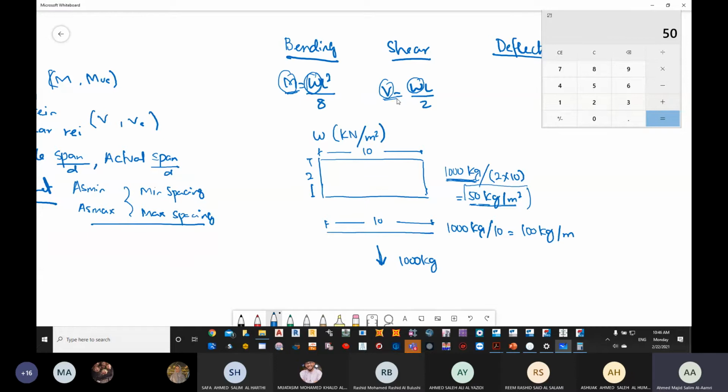And the shear check is without links or reinforcement in case of a slab because of the less loading in the element. So bending and shear, when it comes to slab, once again, are not that critical, and the reason is that the loading is distributed into a larger area.